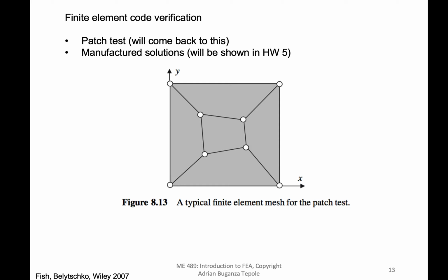So for the patch test, basically you want to check some basic properties of your finite element interpolation. And a typical finite element mesh for the patch test is shown here. Typically you have a very, very coarse mesh with a few elements, and then you're going to test things like, for example, whether or not this simple mesh can satisfy some properties of the solution, can represent some basic types of solutions. And again, we'll talk more about this in the next class.